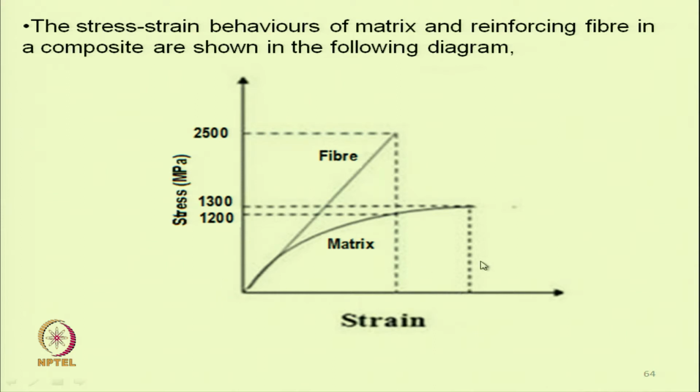So, while extending, although the fiber, the reinforcing material, is taking maximum load, due to its lower extensibility, lower breaking elongation, fiber will break first. At that time the load on matrix is less than the breaking stress of the matrix. So, that stress on matrix will be 1200.